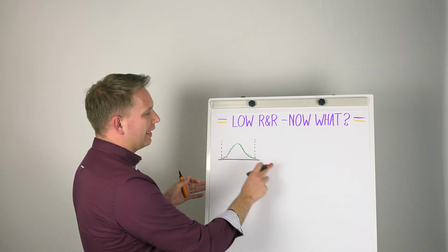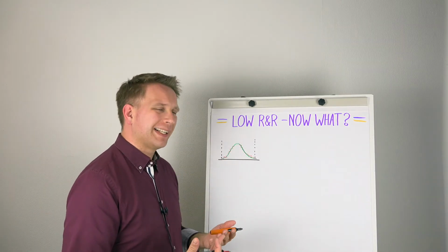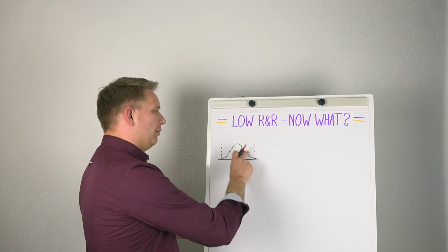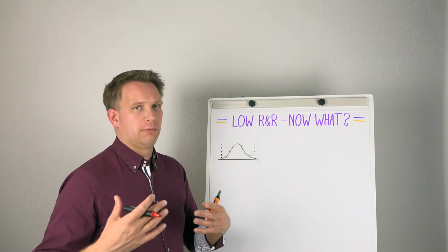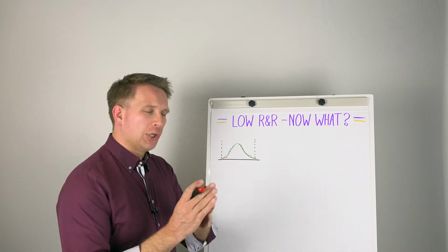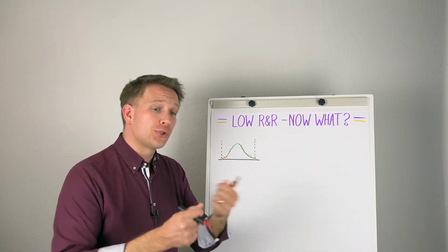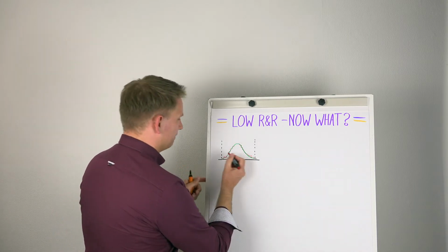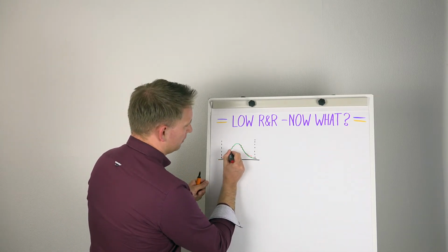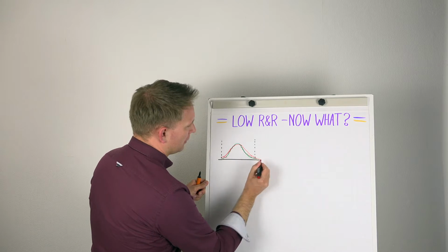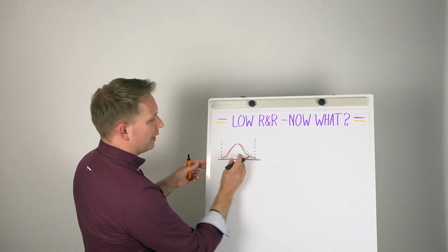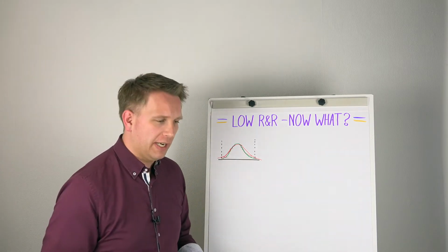And if everything has a little bit, then what you basically see is that instead of the real part-to-part variation, your observed variation will be slightly bigger due to also some variation coming from the measurement. So you're actually seeing a bit more variation.